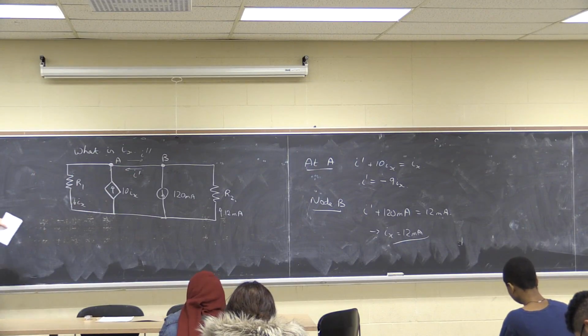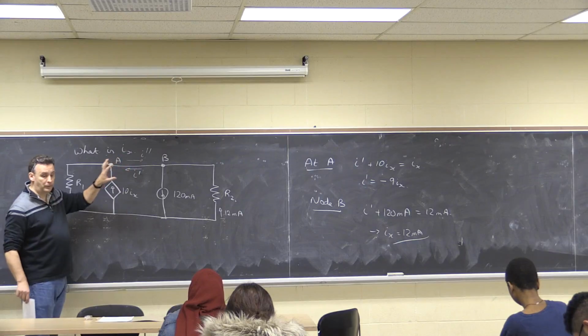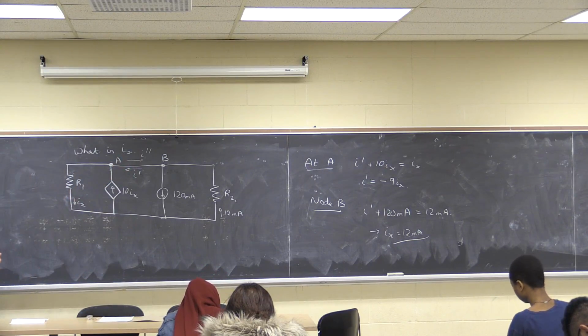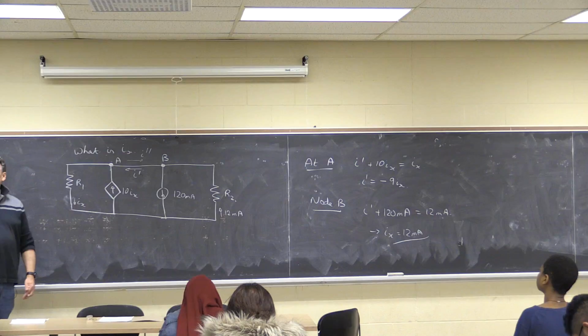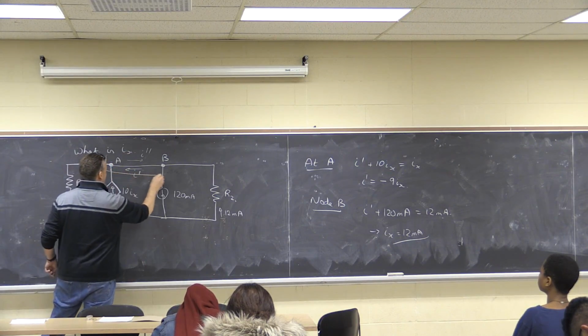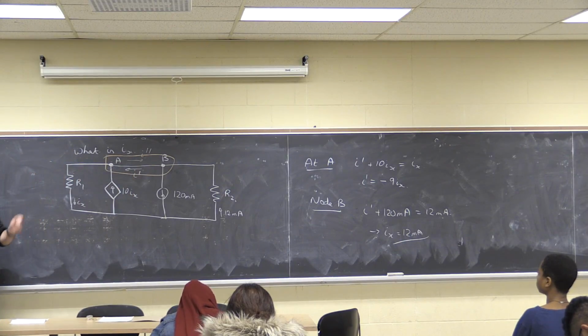The key point is you can define currents and things. We're conserving current around this, so we're looking at the nodes. The other thing, I will talk about this later, and I'll just flag it now as an example. We've got an example of something we'll meet in a few lectures' time, a supernode. A supernode is essentially if I put a box around these two nodes, I still apply Kirchhoff's laws.